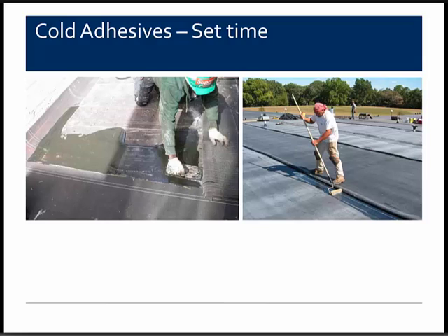Now, the tack test is typically when the solvent is allowed to flash off until the adhesive does not string or transfer to a dry touch. This is usually recommended to be continually monitored throughout the course of using the adhesive, whether it's any time of the day.